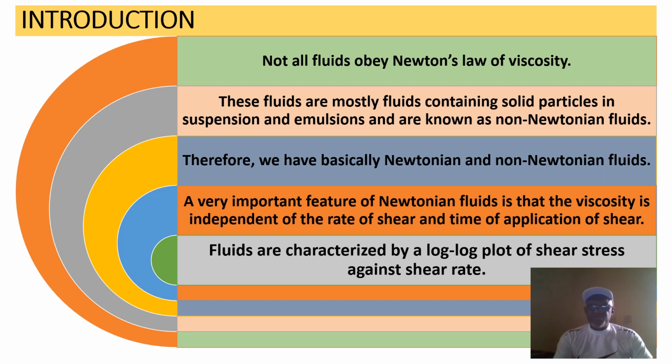Not all fluids obey Newton's law of viscosity. Like we said, the fluids that obey Newton's law of viscosity, we call them Newtonian fluids. But those fluids that do not obey Newton's law of viscosity, we call them non-Newtonian fluids. These fluids are mostly fluids containing solid particles in suspension and emulsions. Therefore, we have basically Newtonian and non-Newtonian fluids.